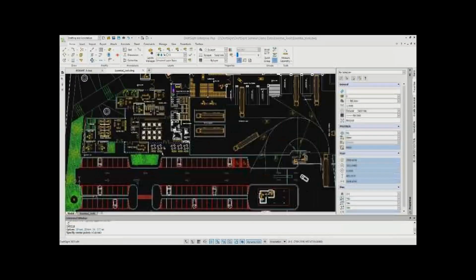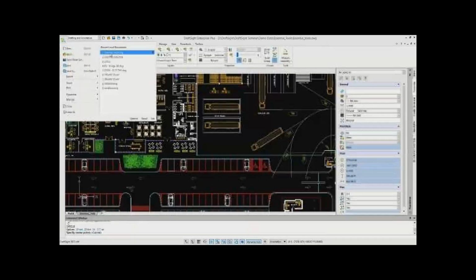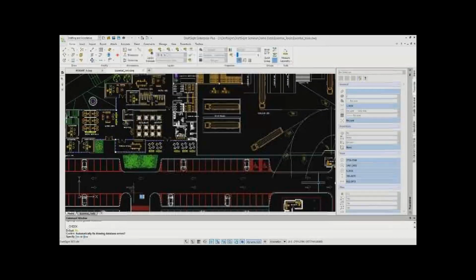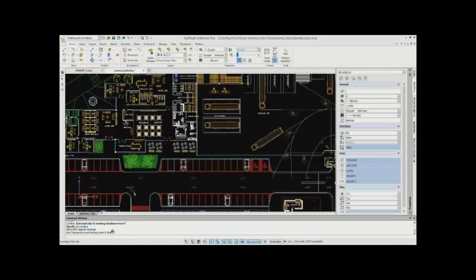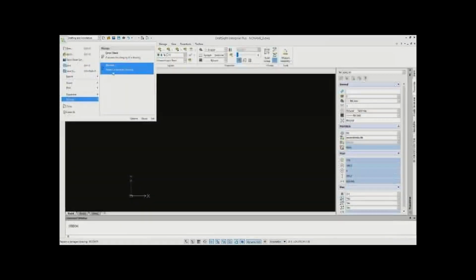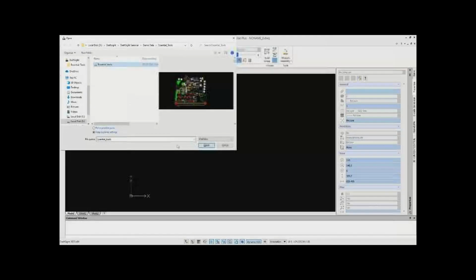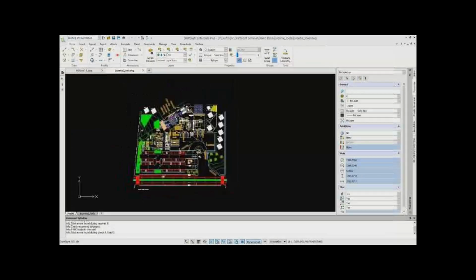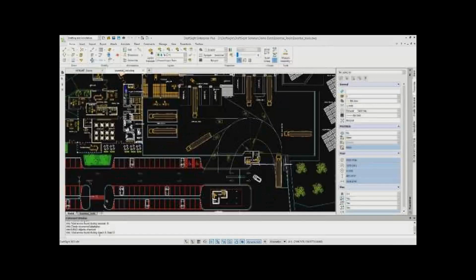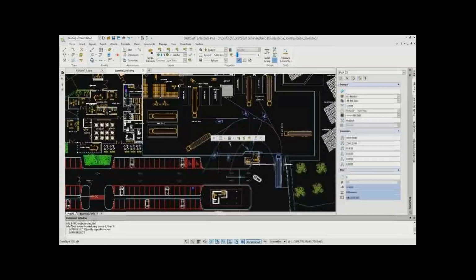Following that, let's look at two recovery tools, like error check. This tool is helpful for finding errors that develop while creating the drawing. For example, let me create a drawing, and if there is an error, it will be notified in the command window. After that, we can check it with the error check entity tool and resolve the error created by DraftSight. We can also recover the same file if you face network issues or something. If the file is corrupted, you can recover the file.